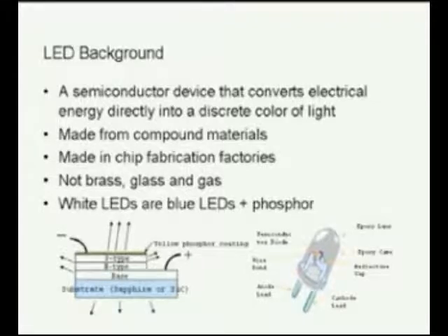In the lower right is a traditional looking LED. The small bullet-shaped device is often termed a 5mm LED, or in some cases a T1 3/4, using the traditional lamp nomenclature for describing the diameter of lamps in 1/8 of an inch. In this case, the lens itself is made of epoxy. More recent devices use silicone.